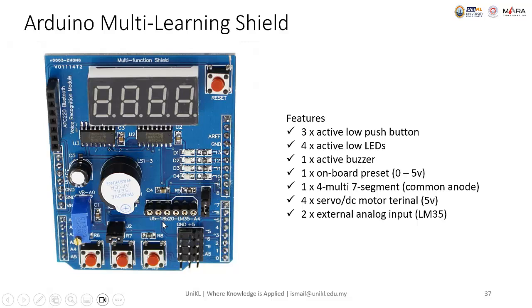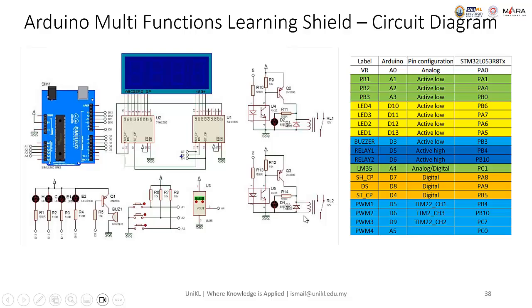This one is the DS18B20. Actually, one pin is VCC and the other is ground, and the middle one is for signal or data. This is the connection circuit diagram. You can see it later on.